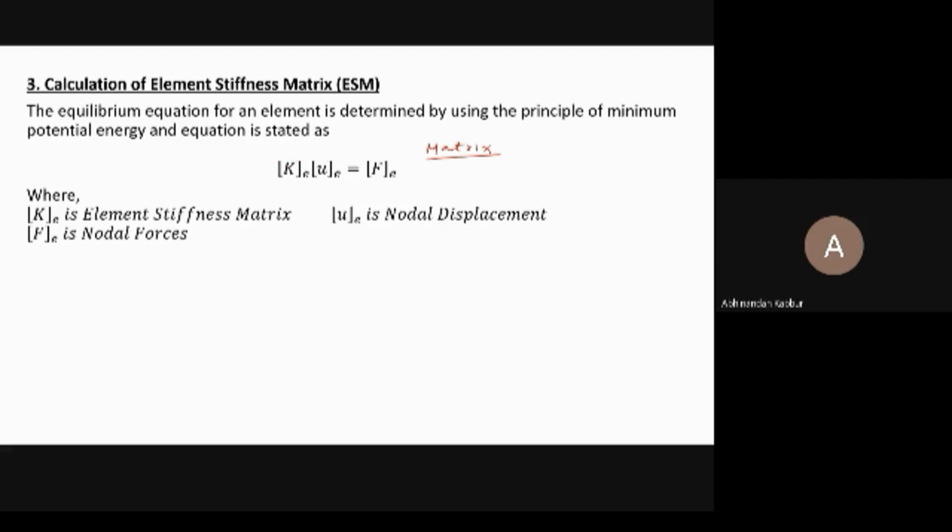Now, this is my equilibrium equation. This is what we call an equilibrium equation. I obtained this equation from Hooke's law. How? The force is directly proportional to the extension in the spring. After removing the proportionality sign, I get a proportionality constant, that is spring stiffness, K, into X. Now, instead of X, here I have considered the displacement in the form of U. Therefore, my F will be equal to K into U. So this is how we have obtained the equilibrium equation from Hooke's law.